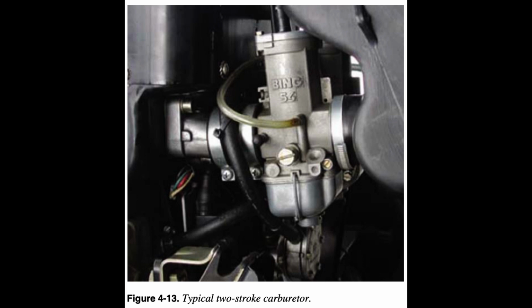To maintain the correct fuel/oil/air mixture, the main jets are usually changed for smaller jets based on the density altitude of the base airport. Operating from low altitude airports and climbing to altitude where the mixture becomes rich for short periods is acceptable. Operating an aircraft at a lower altitude airport with the jets set for higher altitudes will create too lean of a mixture, heat up the engine, and cause the engine to seize.